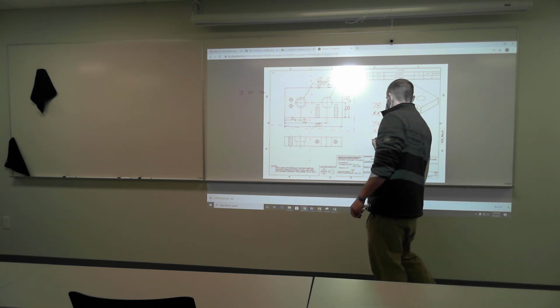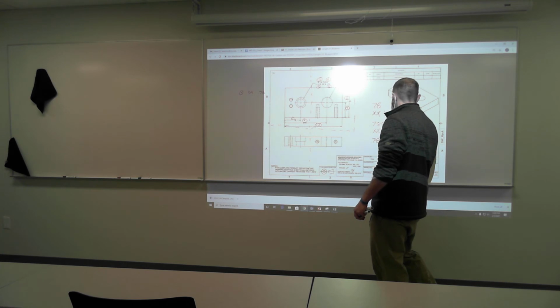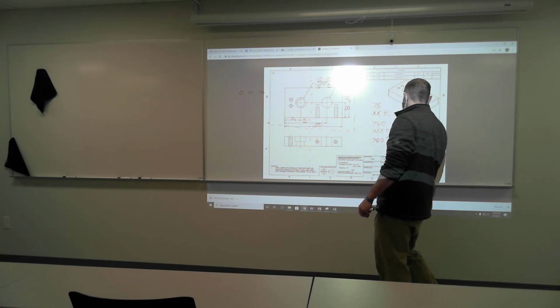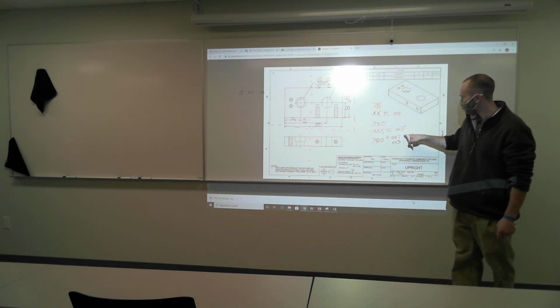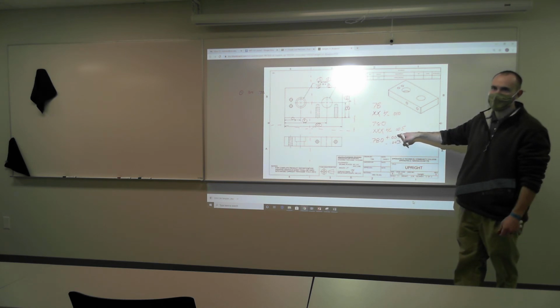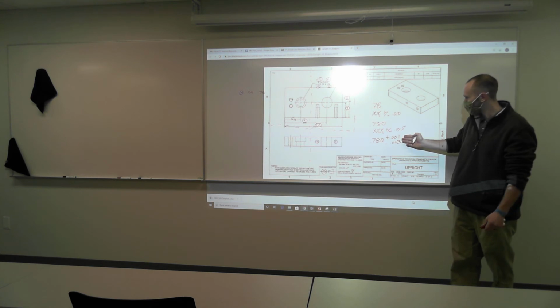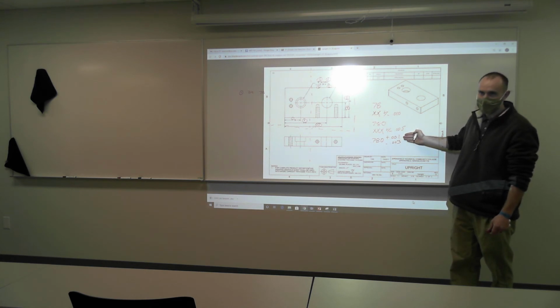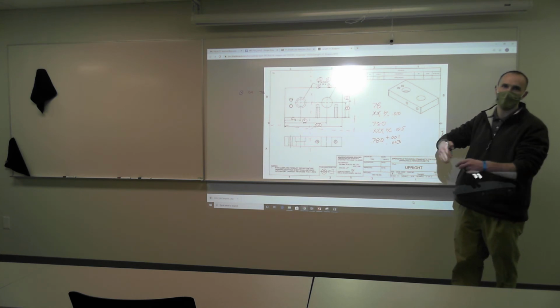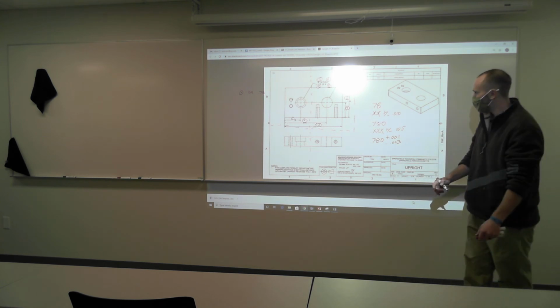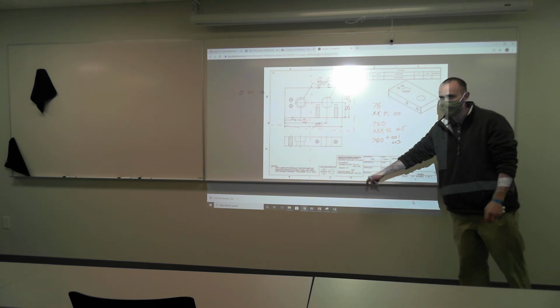Okay, let's say we had this. If you have the tolerance stated next to the dimension explicitly, that's just saying we're not using defaults. We need something other than defaults. It would get very cumbersome if we had to do this for every single one. If we had to state +5, -5, they'd be all over the place. They take up too much room. So you have to know that those default values are right here in the title block.